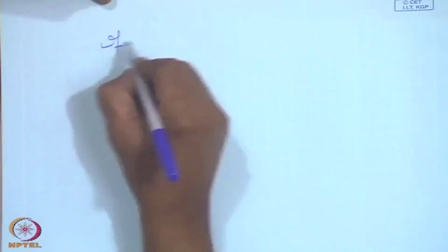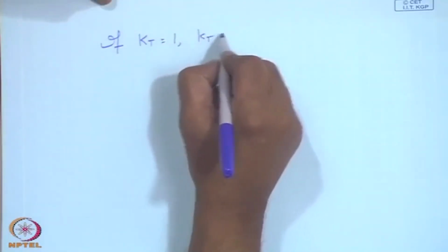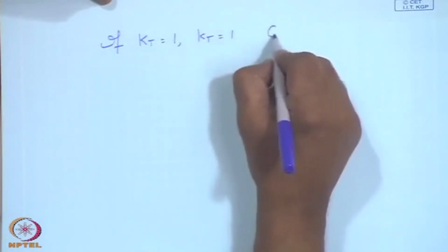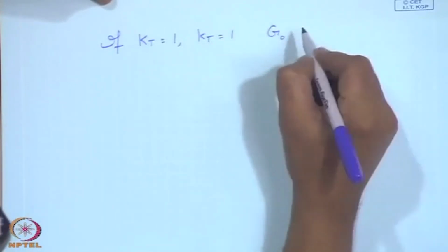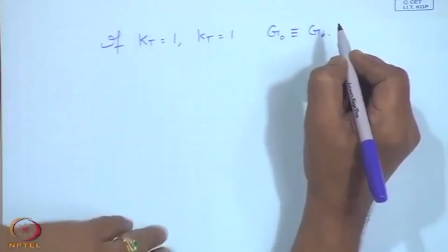Now, what did we achieve by showing this? What we realized is, if the clearness index has been 1, we know that extraterrestrial and terrestrial radiation will be the same, there will be no diffuse radiation.